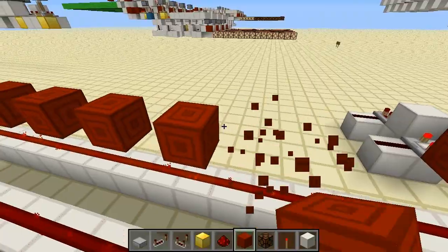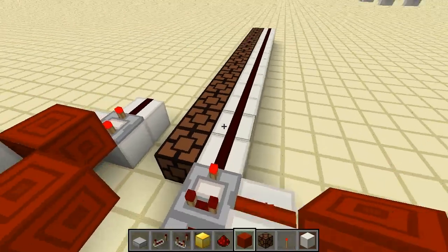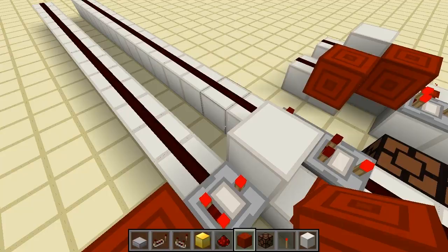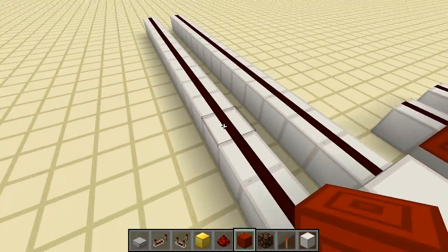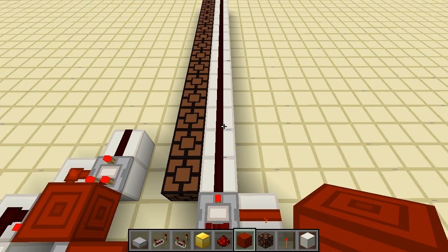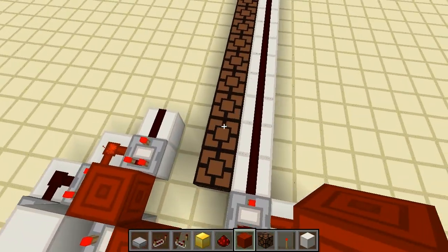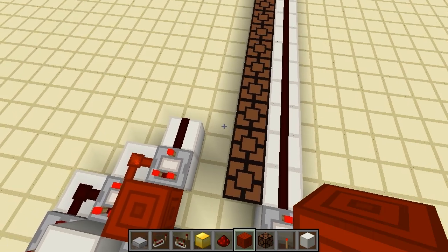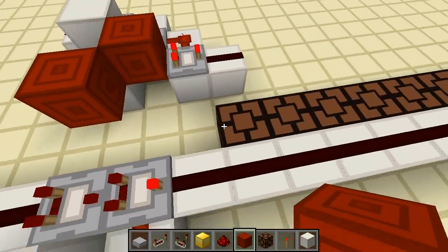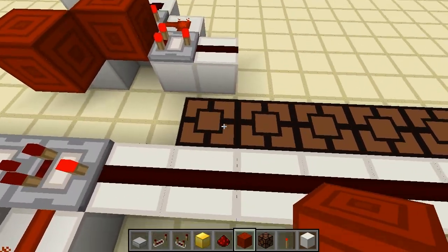And if you mess around with this, you see that this little circuit is giving us the sum of the two inputs minus 15. I don't know what I was talking about before then. Apologies. So between these two circuits, we have detail on the entire range from 0 to 30 of the sum. And also, if we take 1 off this, we see that we get the sum of the inputs minus 16.